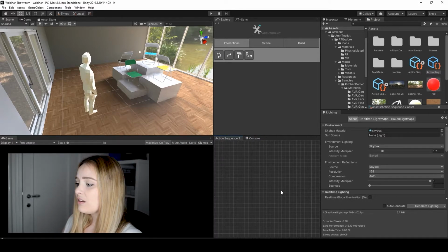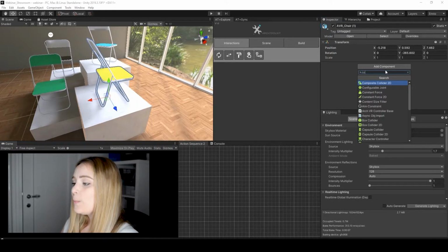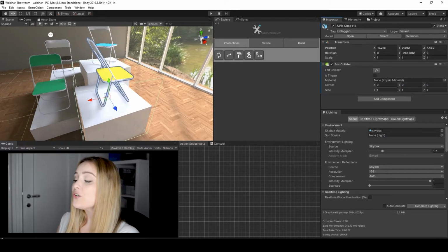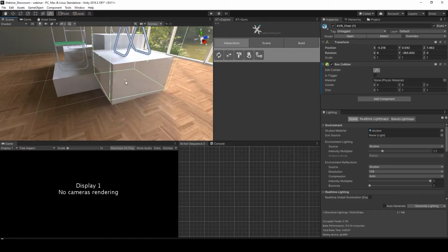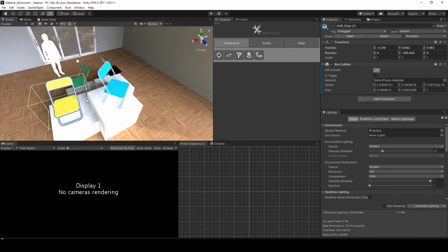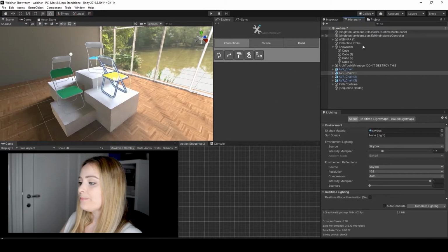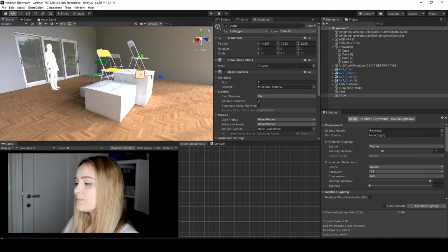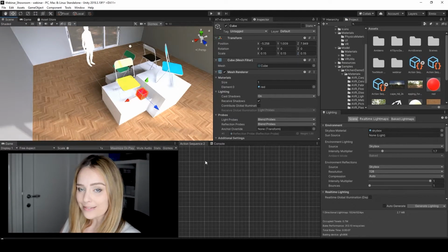Let's focus on the cause for now, on the trigger, which is the click on the chair. To make a chair clickable, we need to add a box collider. So we'll add the component of the box collider to the chair and adjust its size with a handle. Now we need to add a cube. This cube, which we will paint red, will become the button that we can click on to go to the website. Let's recreate the diagram we previously talked about in the action sequence.